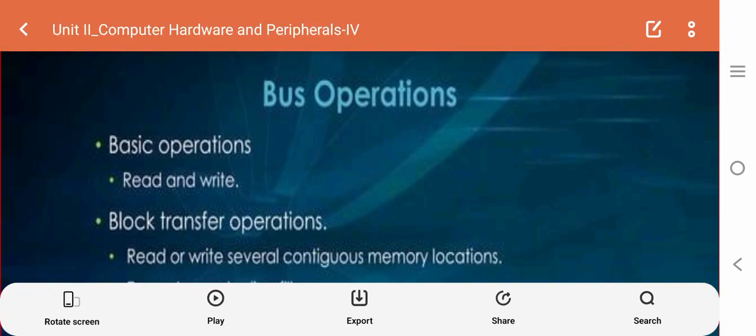Now tell me, what are the advantages of the bus system? The bus system simplifies computer wiring and design. It allows all components to share a common communication path, reducing complexity. It also supports easy expansion, and new devices can be added using the same bus line. So the bus provides flexibility, cost efficiency and standardization across different hardware components.